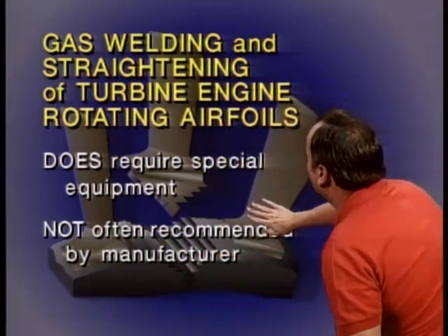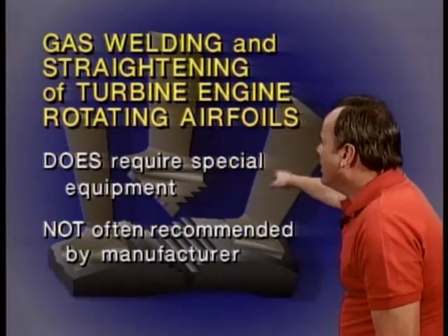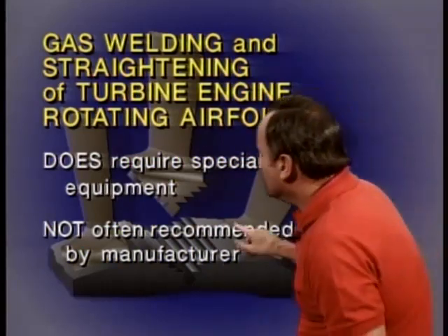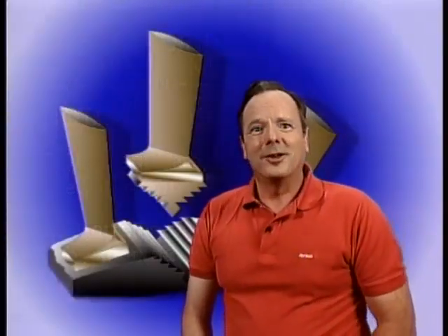So don't plan on doing field welding or straightening of a turbine blade, because it requires special equipment and it is not often recommended by the manufacturer. Fat chance, I think they're trying to tell you right there.